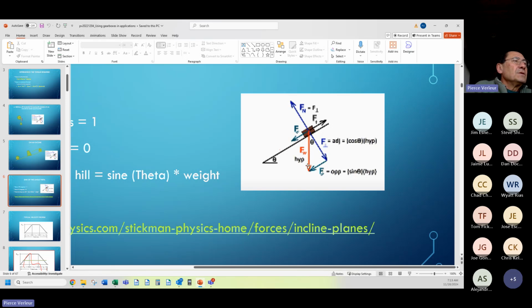Here is your weight of this object. This is the force factored by theta that goes into your calculation for torque. This is your friction coefficients. So you can obtain this data from the customer or through your own calculations if you're the designer.